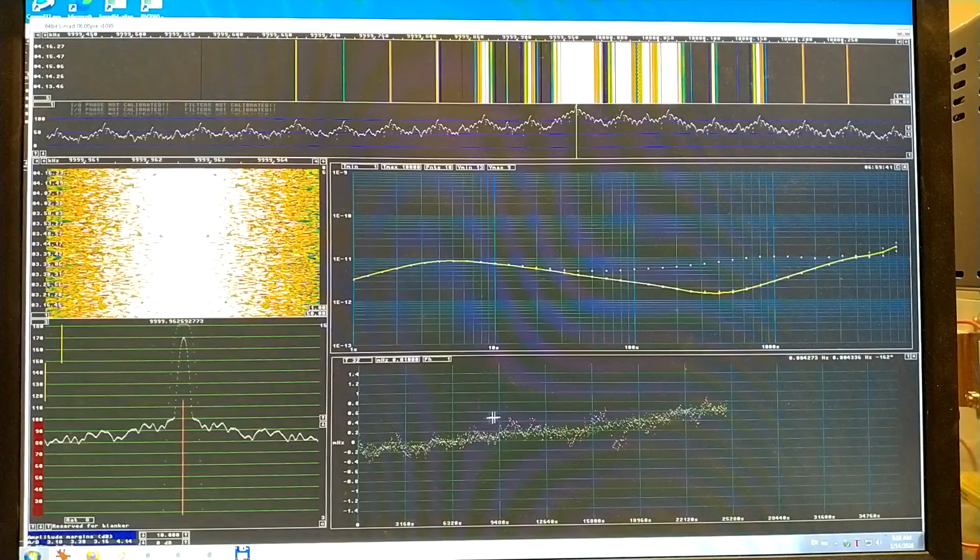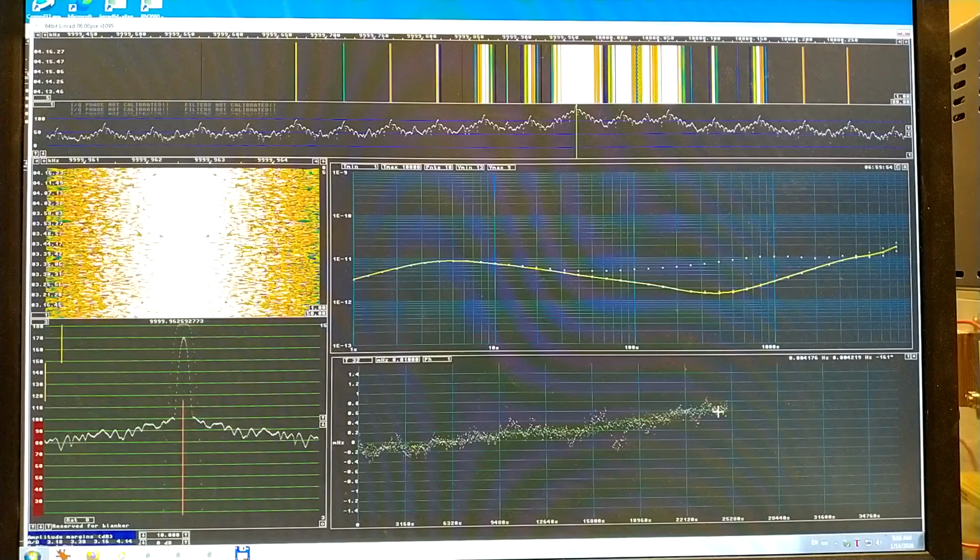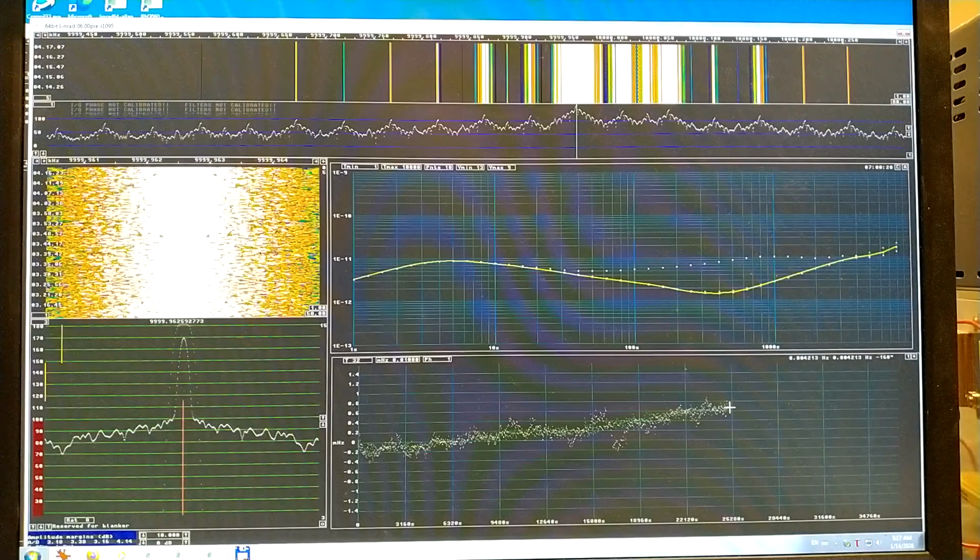After 7 more hours, this frequency versus time graph is still increasing slowly. After all the 7 hours, the frequency has drifted from minus 0.2 to plus 0.6 millihertz. And probably this is the Wenzel oscillator that is drifting slowly, but it could also be the rubidium.